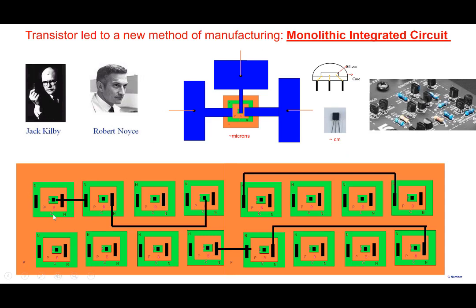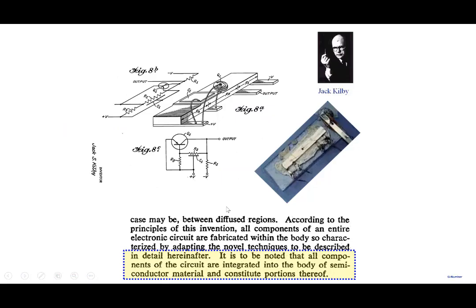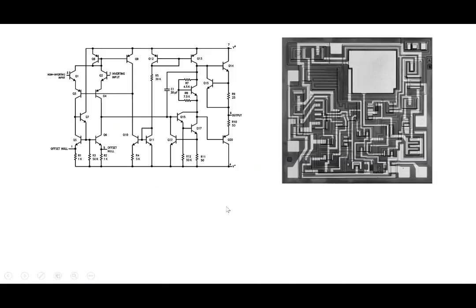The transistor is made by N, P, N regions, which are made by diffusing impurities, N-type and P-type. There's no picking of a component here. There's no picking of a resistor or a soldering of a resistor. This pick and place method of fabrication that you see here is not used here at all. Things are made on the piece of silicon and integrated on the piece of silicon, the wires and all that. So a new method of fabrication allowed very compact circuits to be made.